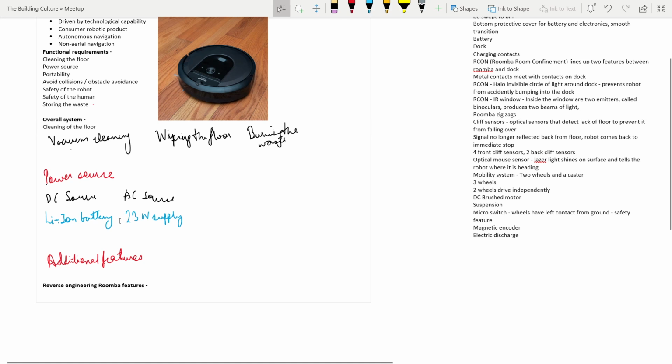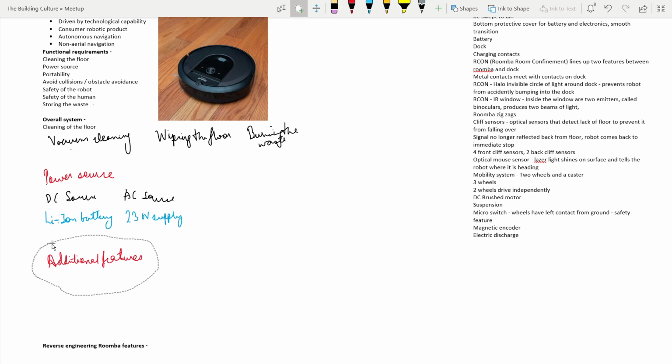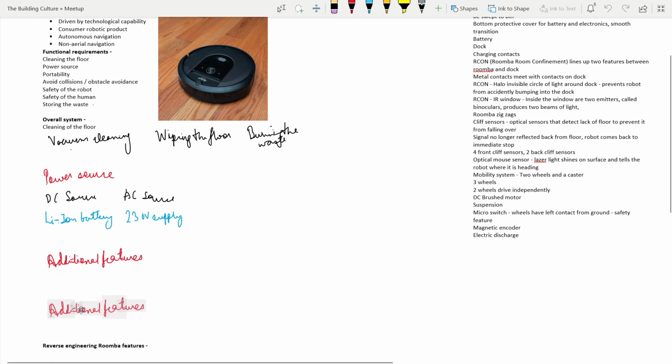What I think is important in portability is defining the dimension, like how much maximum size this thing will be. Will it be a small dimension thing, like a box of 30 centimeters, or is it a big thing? Because if somebody imagines a cleaning robot, everybody in the beginning will think it's a big thing. Before Roomba came, robot meant a big thing. Yeah, that makes sense. Then dimension definition is important to know. Then you can imagine what sensors will fit in, because if you have dimension clarity, then you know what kind of sensors you can fit in.